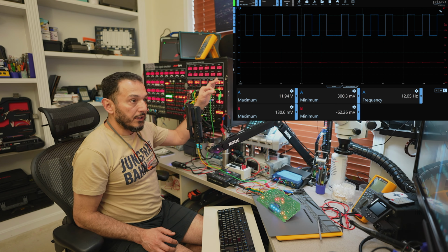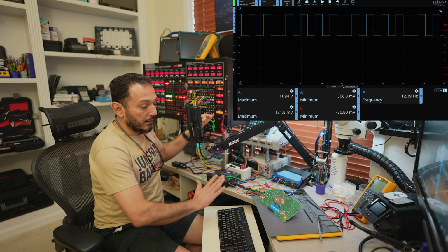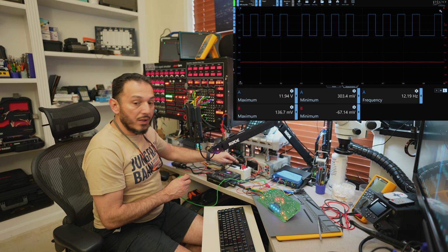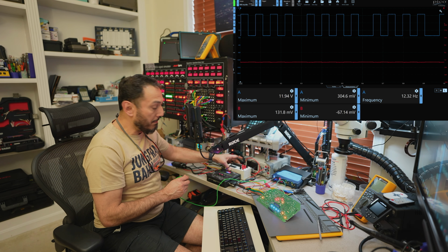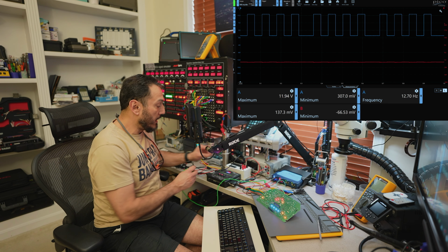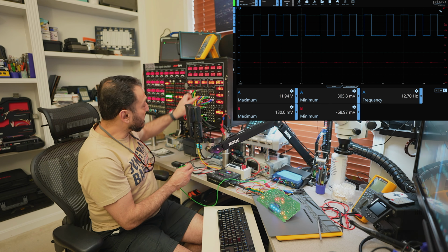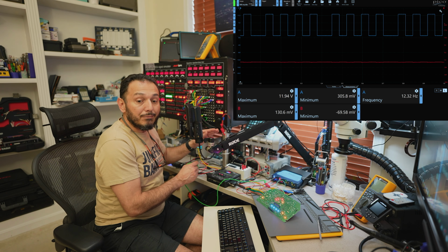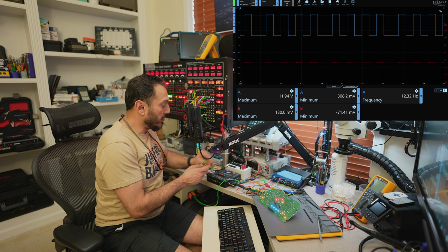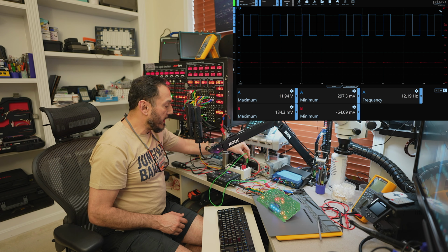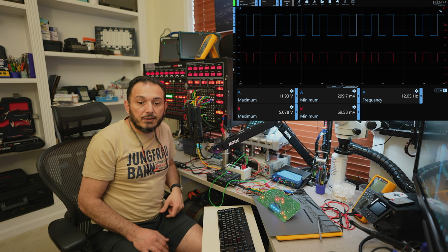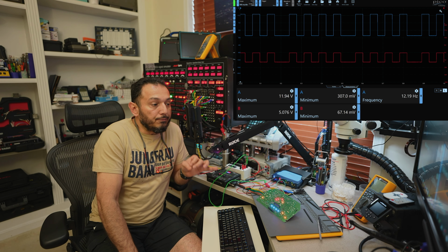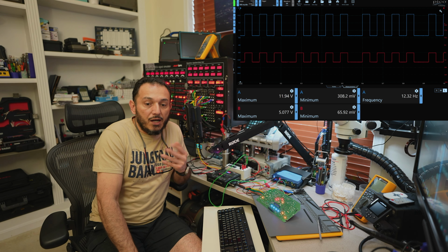So right now on that red, I got nothing but the cluster connected. I am providing a 5 volt reference through a 10 kilo ohm resistor on my bench. I have a decade box. So this black wire is connected to my 5 volts in here, going through a 10 kilo ohm resistor. That's very important because otherwise you can damage the cluster, right? So now I'm going to connect this, and now let's see what we got. What is that voltage reading now? 0 to perfectly 5 volts. How is this cluster now?